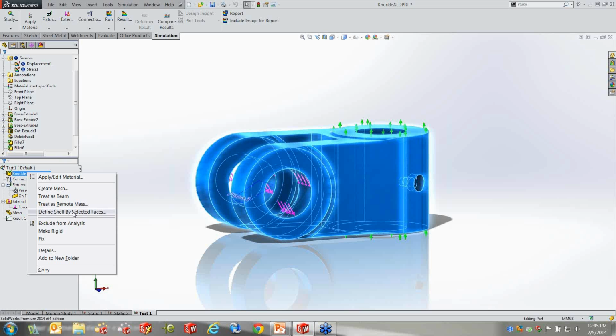For instance, beams are great for weldments. And anytime you create a weldment in SOLIDWORKS and you create a simulation study, it's going to apply a beam to all of the structural members. If you do sheet metal in SOLIDWORKS, that's best using a two-dimensional triangular element. And the software is automatically going to apply a shell mesh to that.